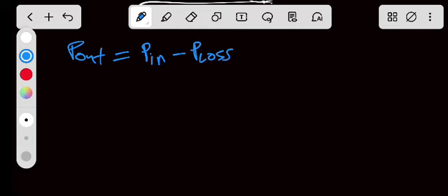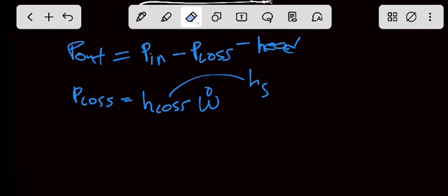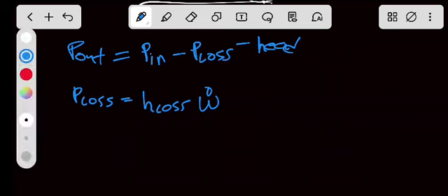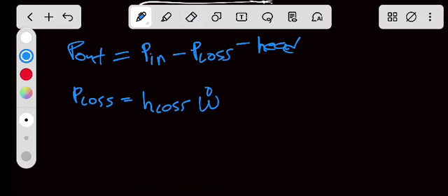You'll get this from the head loss. So what will be power loss? Power loss is equal to head loss multiplied by the flow. Obviously, sometimes this will be H loss of the friction. But even the friction, still it's a head loss. HF, this formula is one and the same thing. This is a friction, still it's a head loss due to friction, or in the pipe, still the head loss in the pipe. This is simply H.